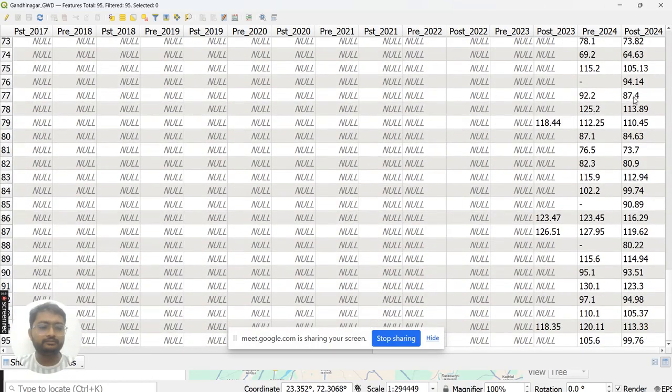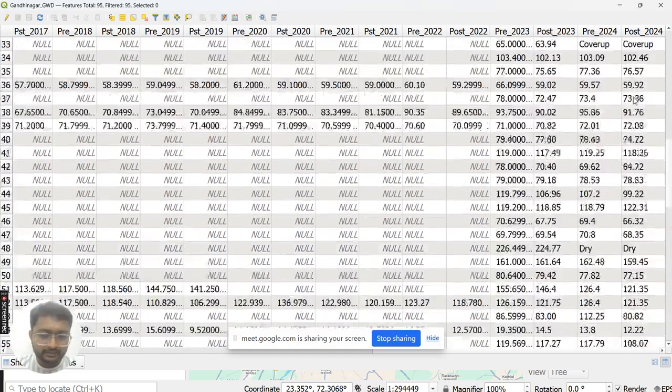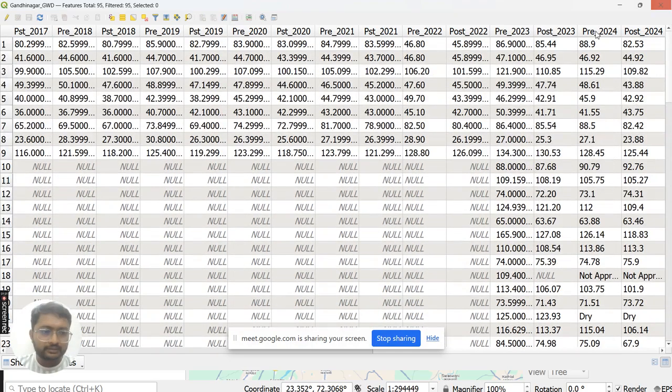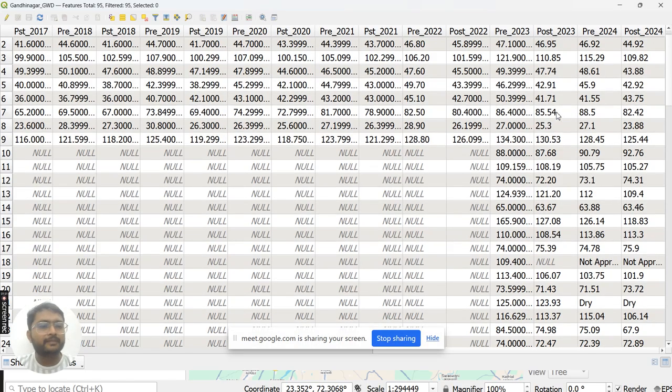Nearest values are available. Yes? Only nearest values are available for interpolation. No, what I'm saying is these columns, these attributes, are not available for interpolation. This pre-post 2021 is available, all these layers. But those columns are showing us string values. Yes, exactly, string values cannot be interpolated through IDW. From the data, you would see it as ratio or interval data.